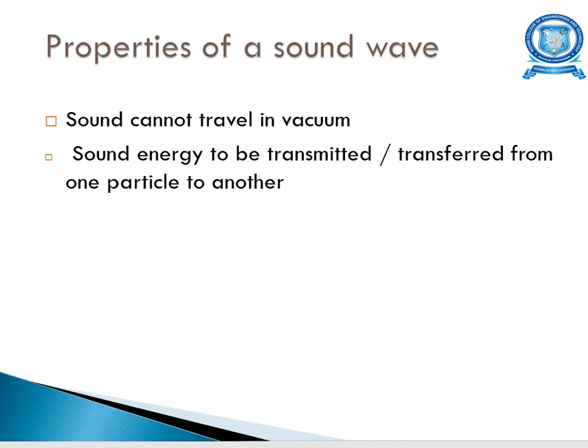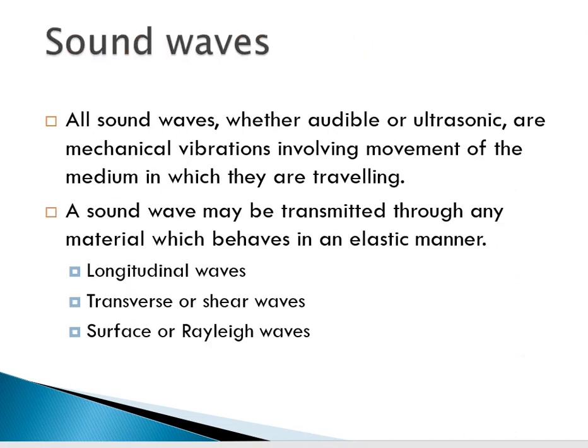Properties of sound waves: sound cannot travel in a vacuum. Sound energy is transferred from one particle to another. Sound waves are transmitted through materials which behave in an elastic manner. You have three types of waves: longitudinal waves, transverse or shear waves, and surface or Rayleigh waves.